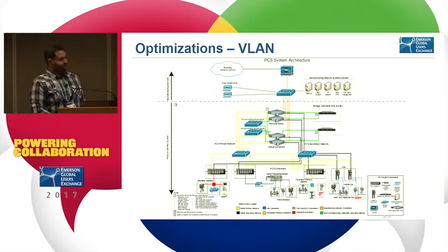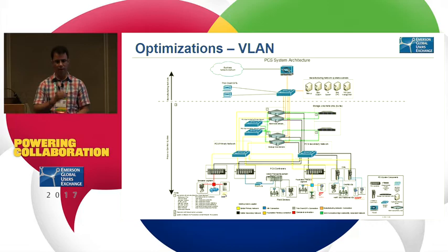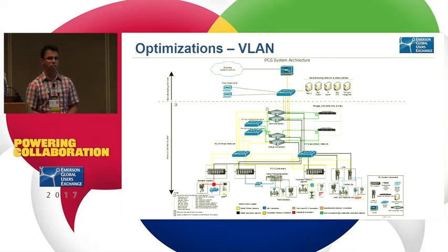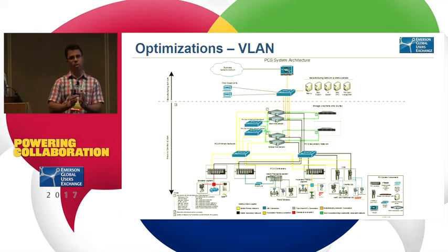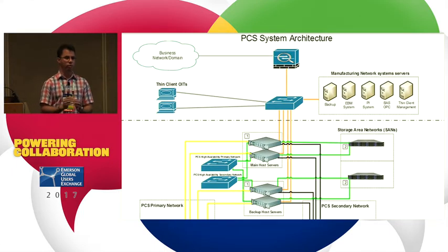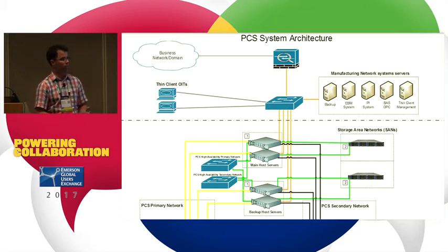So yes, in our project, we take advantage of the bulk part pricing that IT was able to obtain, and we pretty much capitalize on that by connecting all plant-land connections from our servers directly to the IT network. From the IT network, they assign a VLAN to each DeltaV system, and from that VLAN, we communicate to the system outside the DeltaV system.